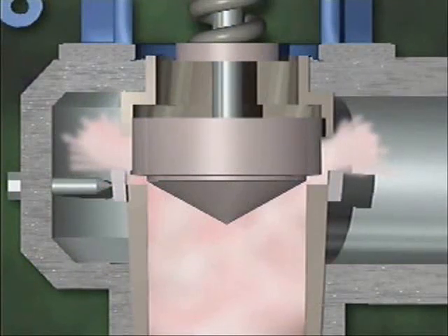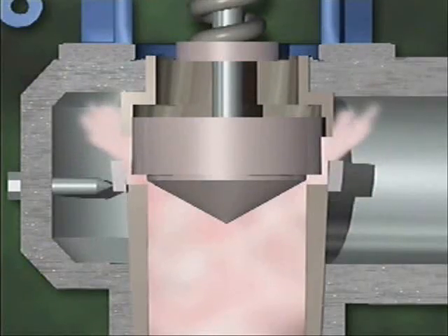You see, the position of the disc in a safety valve is determined by the amount of system pressure and the angle and velocity of the steam striking the disc. When the adjusting ring is in the raised position, the escaping steam is directed right at the disc. The velocity of the escaping steam exerts a great deal of upward force because most of the steam is aimed to strike the disc closer to a 90-degree angle. In turn, the system pressure must drop well below the popping pressure of the valve before the spring can force the disc back onto its seat. So raising the adjusting ring increases the blowdown of the valve.